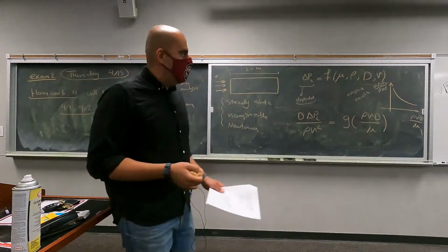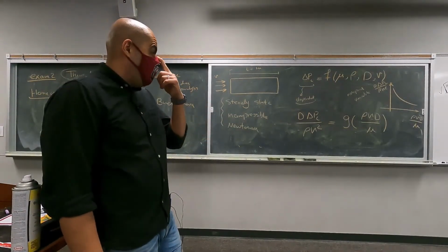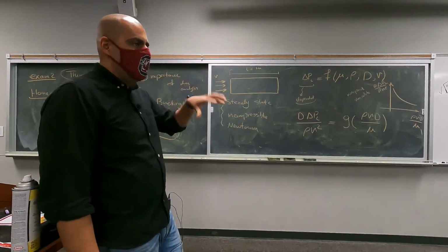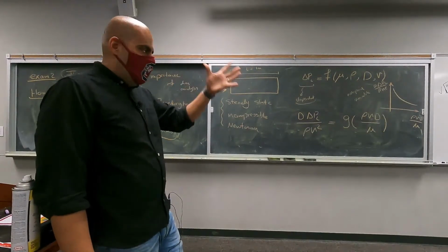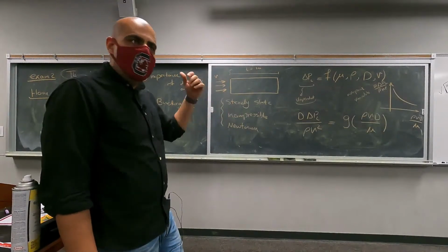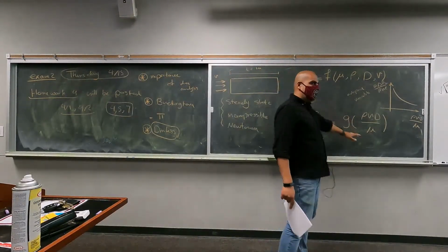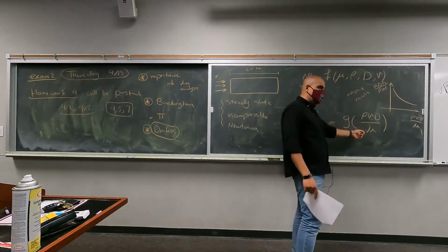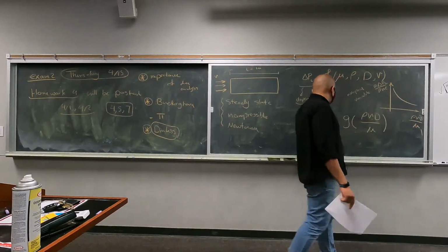It's just an example. So again, just to make sure that we are on the same page, the idea here in dimensional analysis is to reduce the number of parameters, which means that we are going to simplify the analysis. Instead of running 625 cases, we are just going to run a couple of them, like 5 cases. We are going to get 5 data points, and then do a curve fit, find the dependence of this on this.